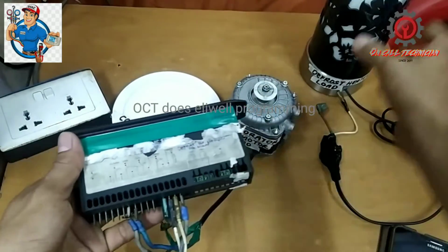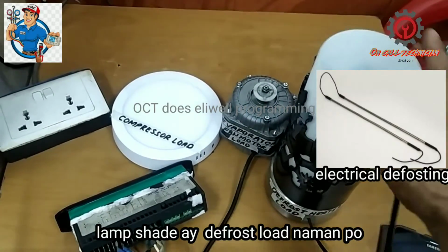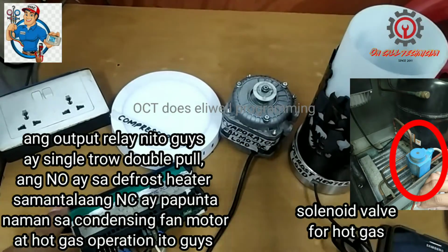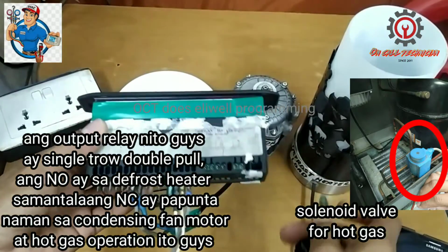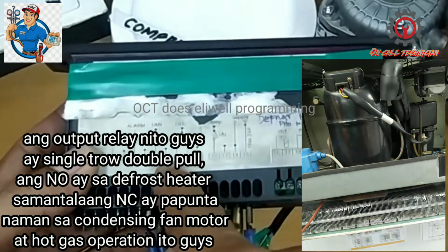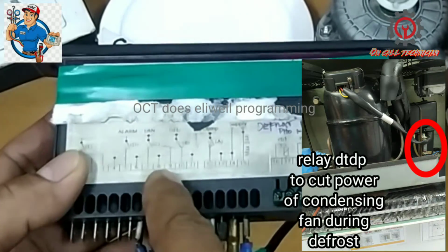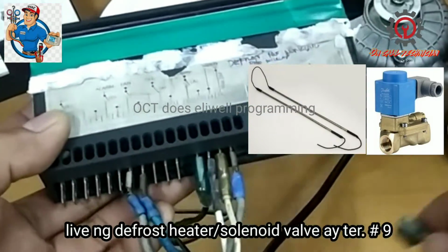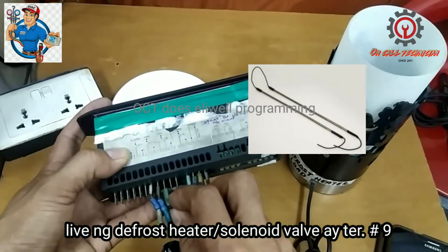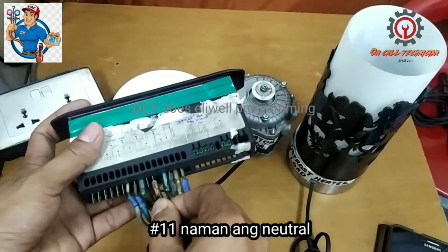Okay, and we're going to install a defrost load, and this is lampshade guys. And for my, this is normally the 9 and 10 is normally closed, so I'm going to put the line to the number 9. Okay, and the neutral I'm going to put to the terminal number 11.